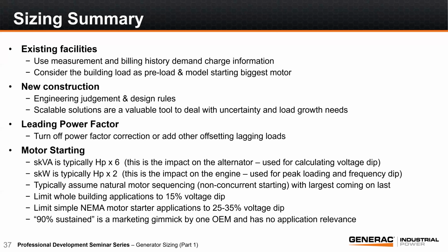Yeah. So one of the things you do want to keep in mind is that we start talking about sizing a generator for standby application versus sizing a generator for a peak demand, peak shaving, or demand response type of application. In a standby generator, you have to make sure that it's certified for standby use from an emission standpoint. That's a whole different conversation we can have. But from a sizing standpoint, we're expecting to see a load factor somewhere in the neighborhood of about 75, no more than 80% average load factor with a fluctuation, right? So sometimes it may be running 50% load, sometimes it may be running 90% load. In a demand response or peak shaving type application, we still expect to see a fluctuating load, but we only want to see a load average not in the 75 to 80% range, but somewhere in probably the 70% range, only because you're adding additional hours to it.